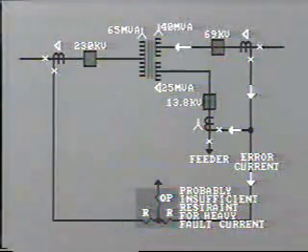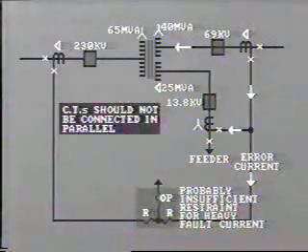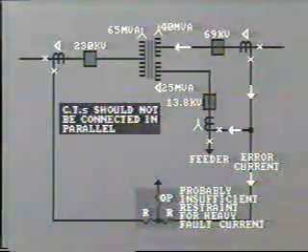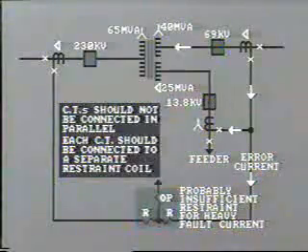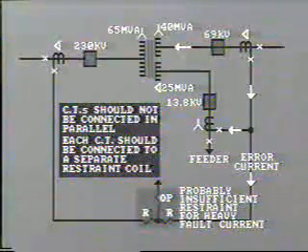For this reason, remember, CTs should not be connected in parallel, and each CT should be connected to a separate restraint coil.